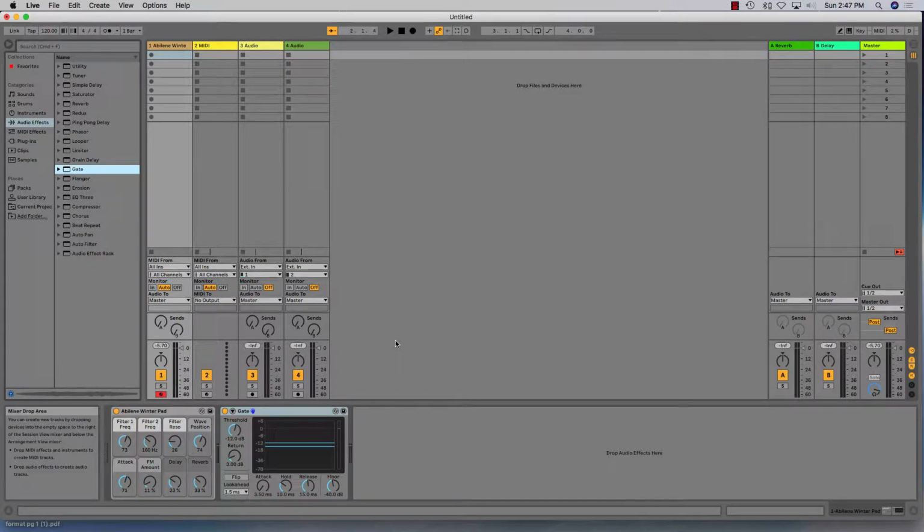When we were working with the PA system in the auditorium, we used the gate setting on the microphones to make sure they were not sending signal to the mixing board all the time. With the gate enabled, audio signal had to be greater than the threshold we set, or the gate would close and no signal would pass through. This is what's going to give us our stutter effect. We need something that will punch through the gate threshold at regular intervals to open and close the gate. Then we'll send that signal through the sidechain of the gate on our synth.